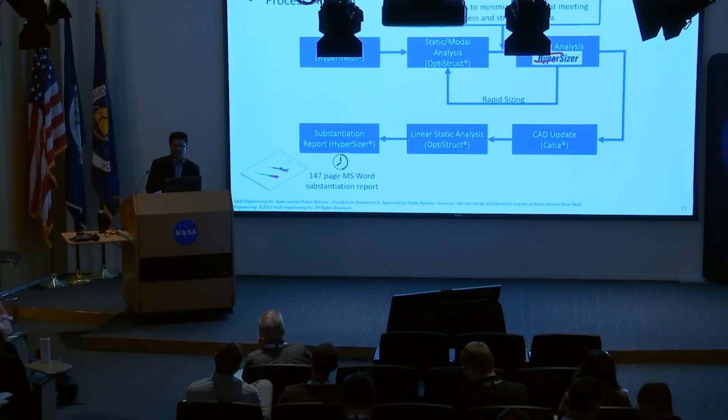I think somebody mentioned yesterday that not only do you get the margins, it gives you how it's derived. It gives you the basic equations and principles for how the margins are derived. Not only that, you also have the spreadsheet, which has all the loads of all the elements. So how the loads were extracted from the DFEM, it's all there. If you needed to interrogate anything, you can go from your report straight to the element number, straight to the spreadsheet, and understand what the loads were. It's just a fantastic way of doing things.